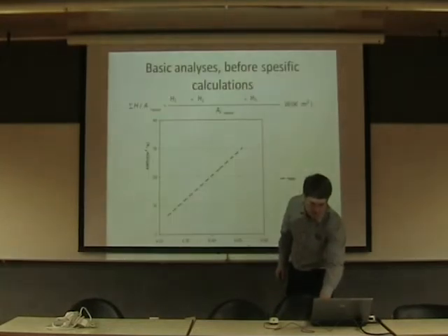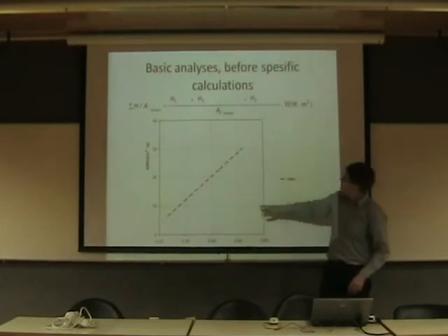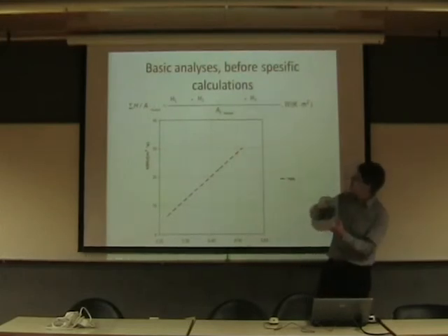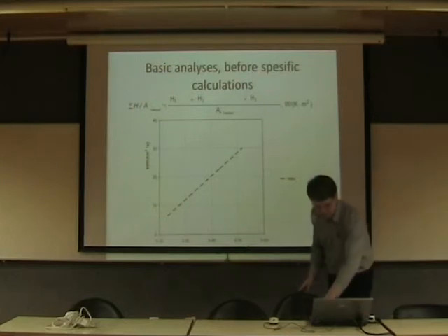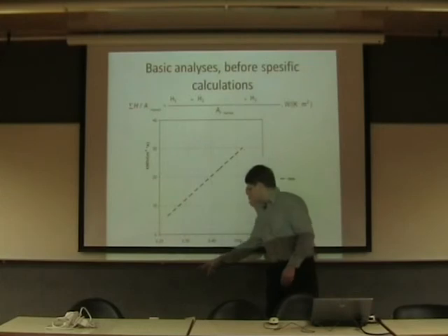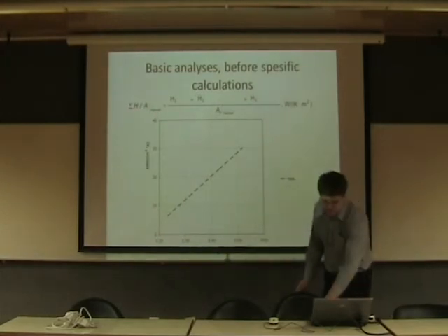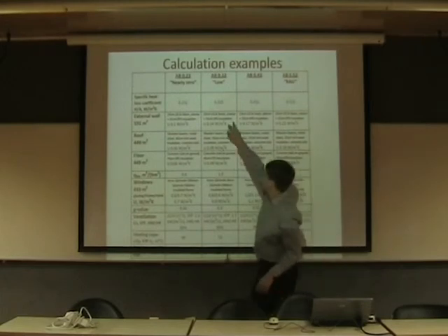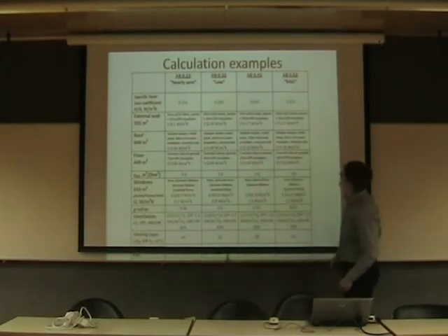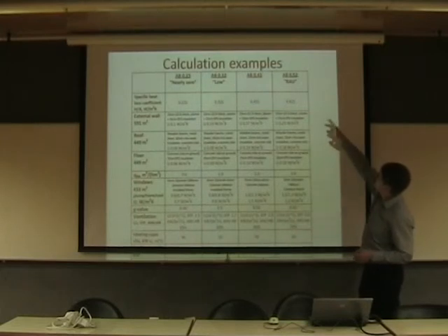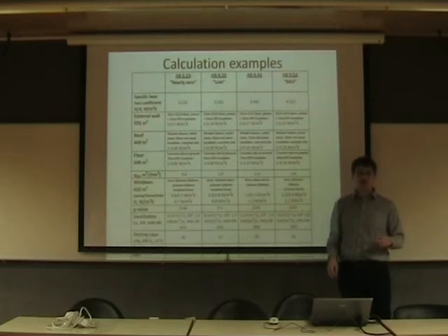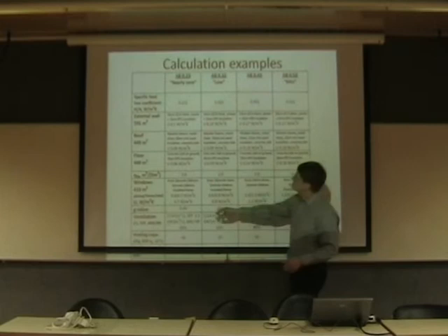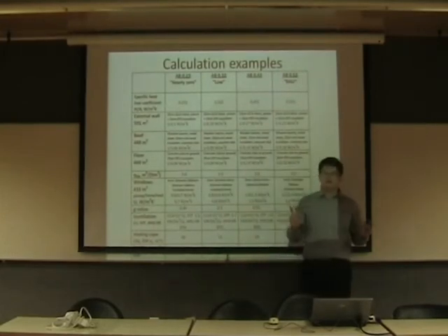This graph shows how much energy we lose from envelopes, thermal bridges and infiltration per heated area. This number can be from 0.2 to 1 or a little bit more. These values are in the first row. We can see the regular building, the kind they are building in Estonia right now, and the last is the nearly zero energy building.